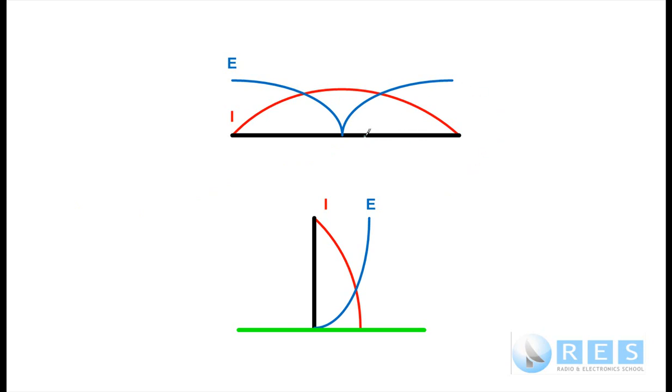But if we were to put ammeters along a dipole, all along its length, we would measure maximum current at the feed point. This is the feed point, this is where it's 70 ohms. You can end-fed a dipole. In fact, you can off-center-fed a dipole as well, but we're only interested in a center-fed dipole. So the impedance is 70 ohms, and that's going to our transmitter. So if we were to measure the currents flowing in this antenna, we would find there's maximum current at the feed point and 0 current at the ends.